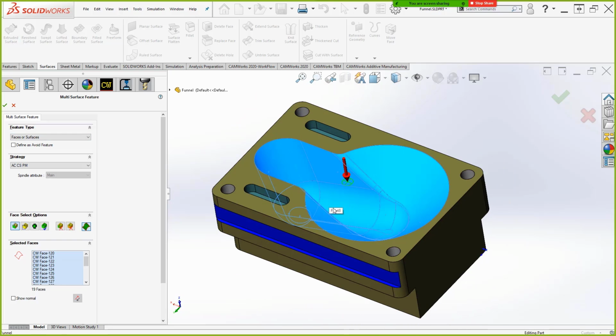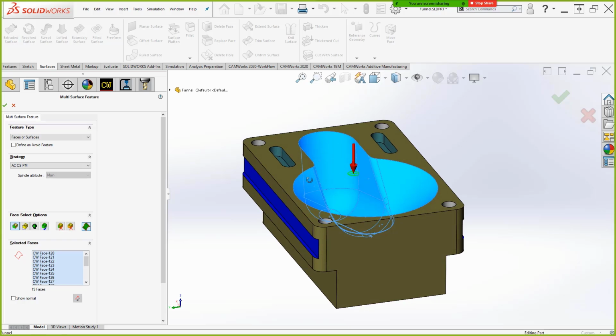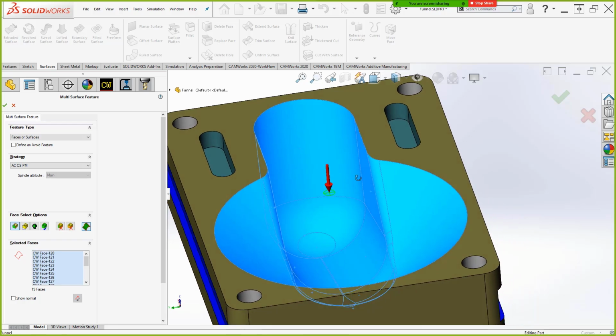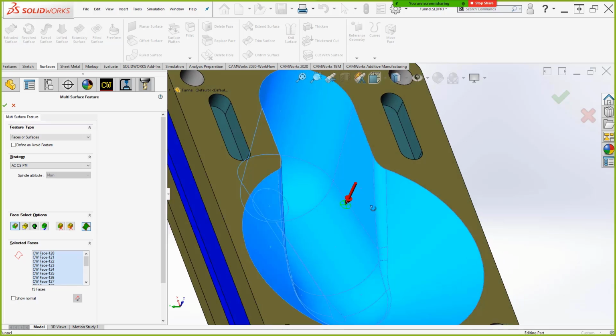A problem with multi-surface features very often is what's the inside of this shape and what's the outside? Well, that terminology and that mode of thinking doesn't make a lot of sense. When I tell a tool to come hit this surface right here, the tool says, okay, I'm going to cut that surface, but what's the inside and the outside of your shape?